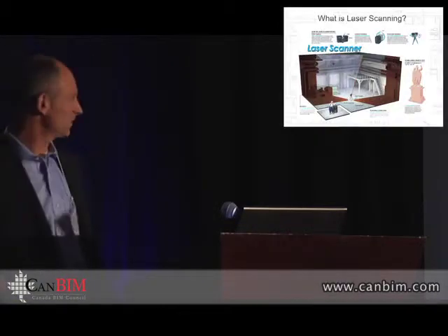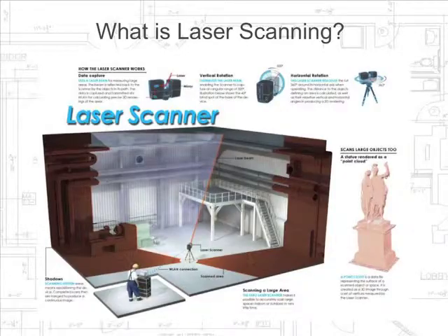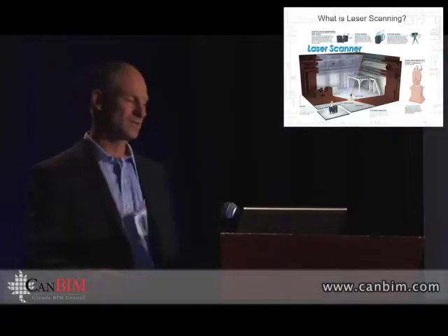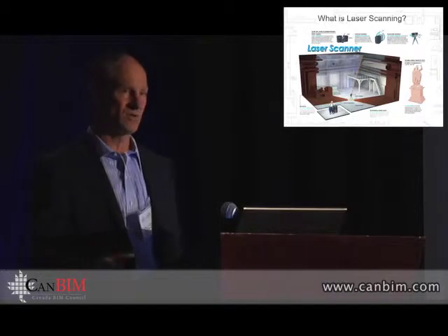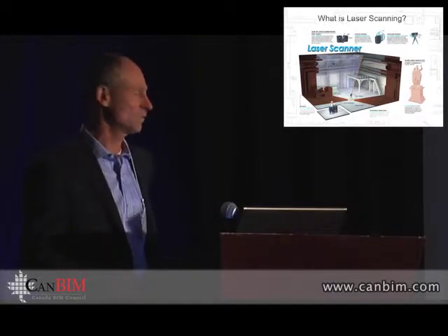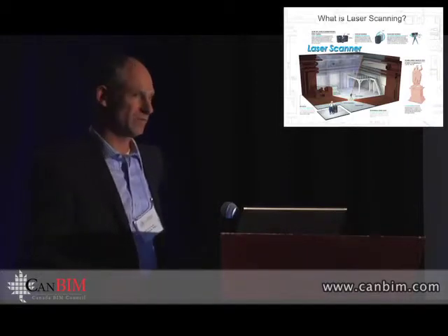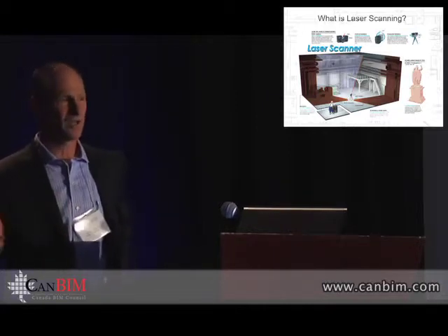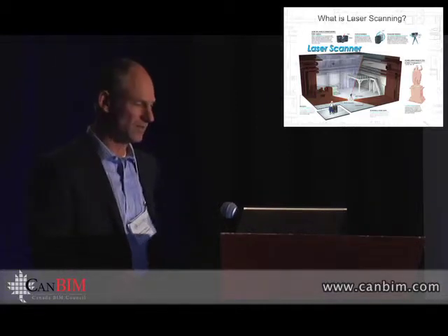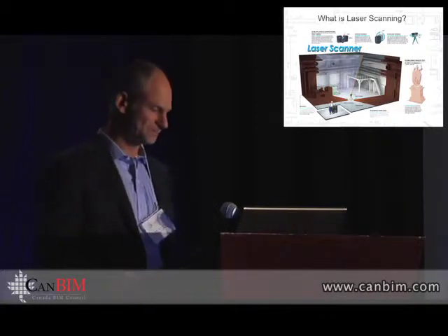So like I said, I'm not going to do that whole slide because it takes a little while. I'm sure everyone in the room, if you're in the BIM world, is pretty familiar with laser scanning, but in a nutshell, there's a couple of different styles of laser scanners on the market that would be used in this market: time of flight and phase-based scanners. The ones FARO manufactures and develops are phase-based. They're both capable. Both have slightly different areas of where you would deploy them. Time of flight, typically slower, but longer range is the way to think about that. And the phase-based tend to be a little bit more accurate.